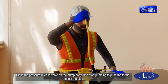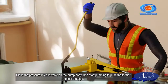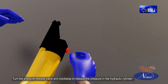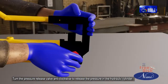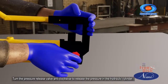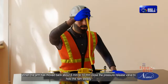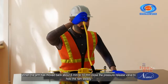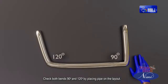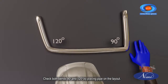Close the pressure release valve on the pump body, then start pumping to push the former against the pipe. Turn the pressure release valve anti-clockwise to release the pressure in the hydraulic cylinder. When the arm has moved back about 6 mm to 10 mm, close the pressure release valve to hold the ram steady. Check both bends, 90 degree and 120 degree, by placing the pipe on the layout.